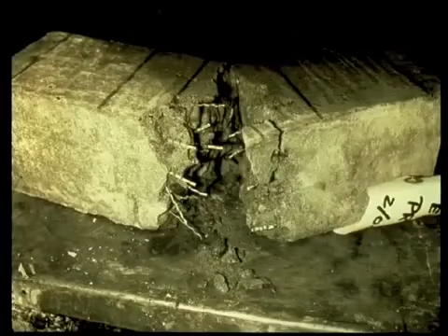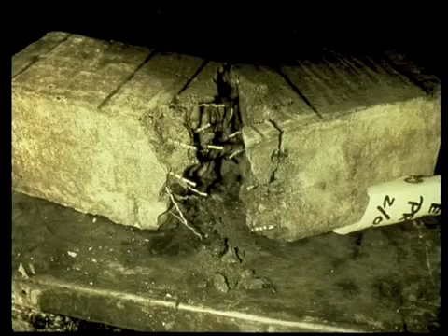The fibers control cracks as the cracks start forming at real local levels. It's very efficient. About 30 to 50 pounds of fibers are used per cubic yard as a minimum. The cost is a little more than that of rebar or wire mesh, but it's money well spent because of the effectiveness of crack control.